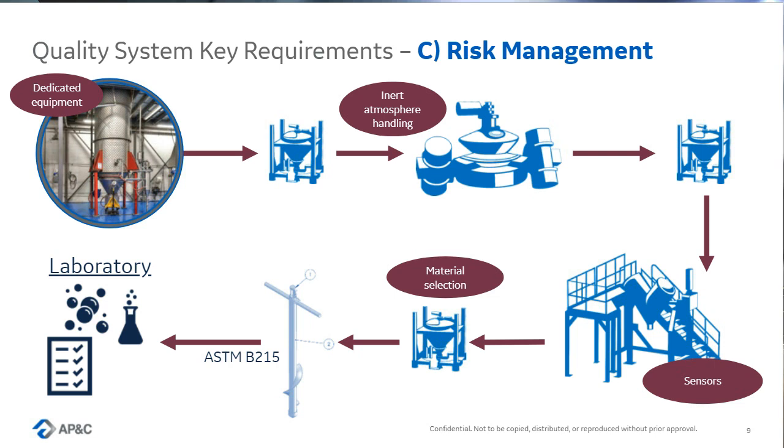And how do you achieve those, risk assessment and risk management? A big part of that is the PFMEA, the Process Failure Mode Effect Analysis. That is really useful, but can be very difficult to maintain for small entities. Obviously, it's going in depth into the process and seeing how it can fail and what's the impact of those failures, and putting mitigation in place to prevent those. So it's a day-to-day thing that you need to follow, but it's really critical.